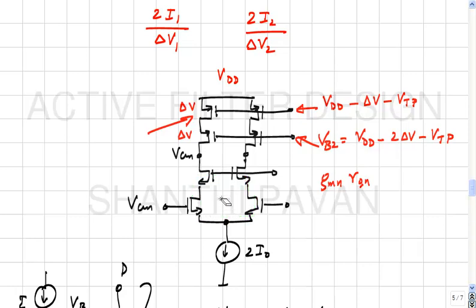The next thing is that now you have two new nodes in the signal picture. Correct? Right. So, the parasitic capacitance of these nodes will add extra poles, which means the GM is not really a GM, but some GM divided by 1 plus S by omega P1, where P1 corresponds to the pole at this node. So, because of this double whammy, you get higher output impedance, but the signal swing possible is reduced. So, this is not a particularly smart thing to do, because the signal swing has come down considerably.